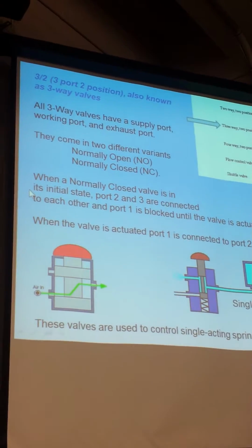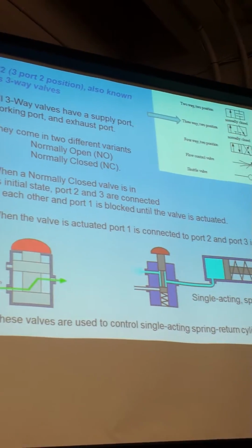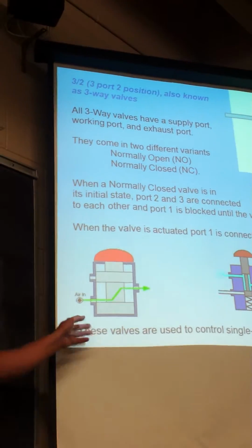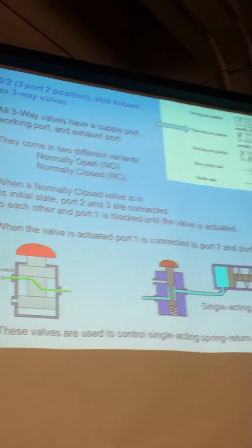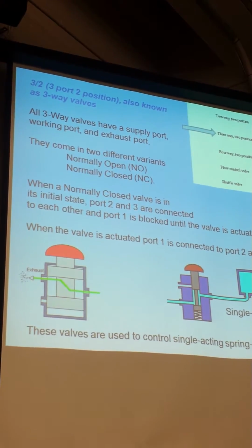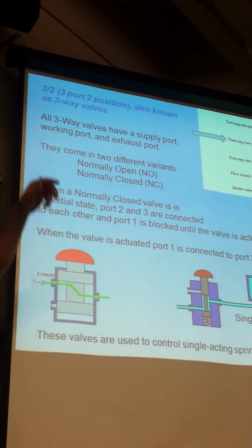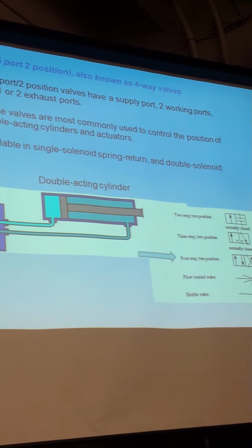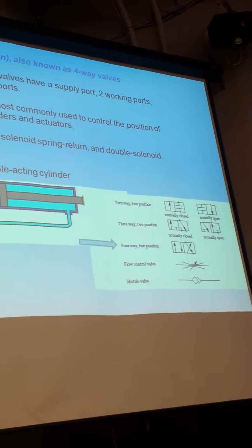Got it, guys? 3-2 valve. What I need you to remember on this is that the valves are used to control single-acting spring return cylinders. Okay? Don't need to know how it's ported, except that there is a normally open, normally closed. We have a supply port working.